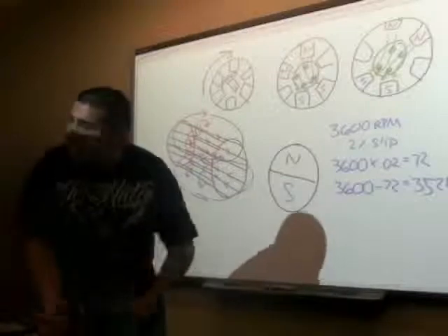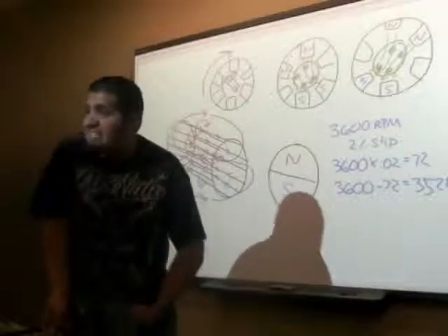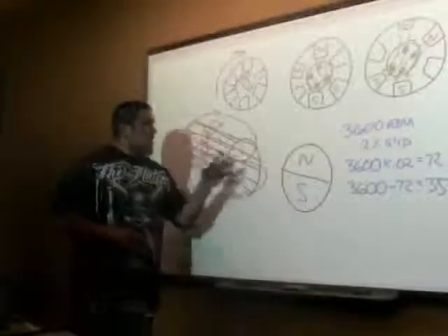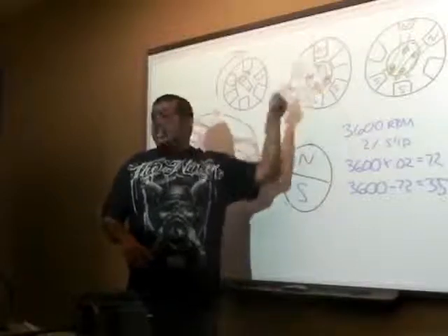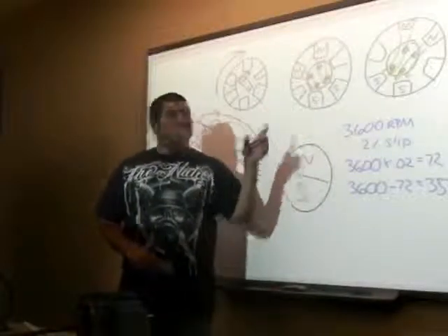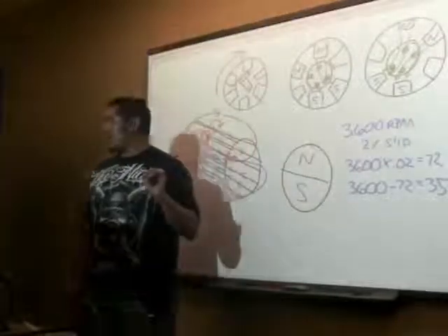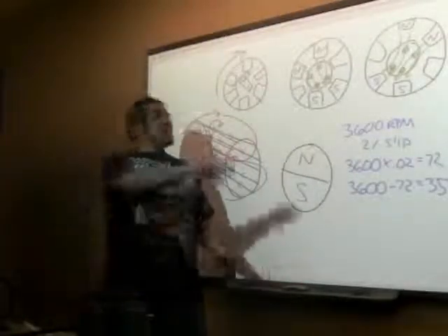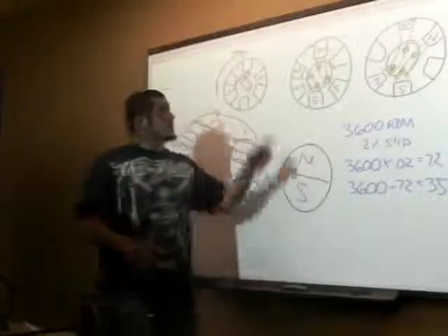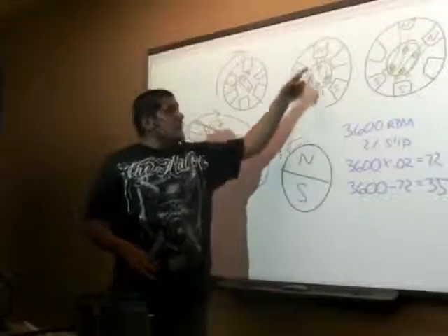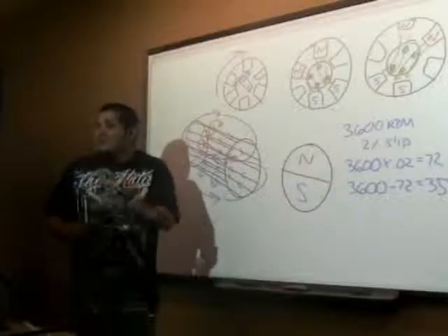It's not locked in. And we'll learn about sync motors, because sync motors actually lock in and stay right with it. Let's talk about this guy spinning around here. The faster it spins, the faster it gets to synchronous speed, guess what starts happening? The less lines of flux that are cutting in. Do you guys understand that? If it starts almost going the same speed as this magnetic field, these lines of flux aren't cutting it anymore because it's catching up to it, right?